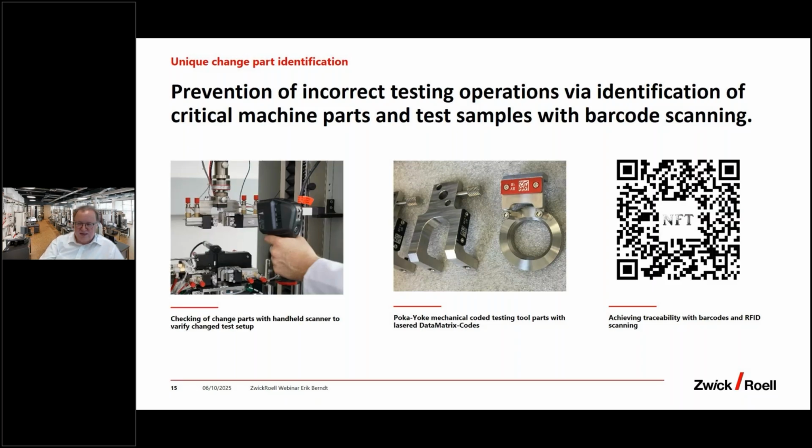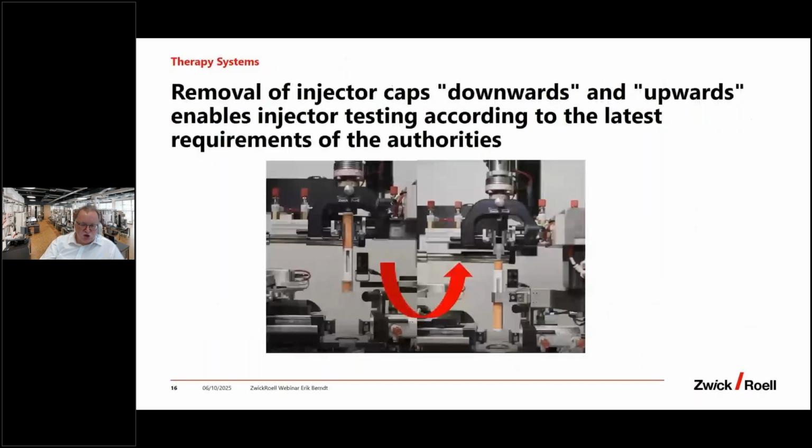Now, what did I say about this change, and why? There are some problems on the market with some autoinjectors and prefilled syringes, especially with more low viscous drugs. There is a risk that when you remove the cap of the autoinjector, which also integrates the safety cap of the prefilled syringe, some drops already get out of the needle tip.